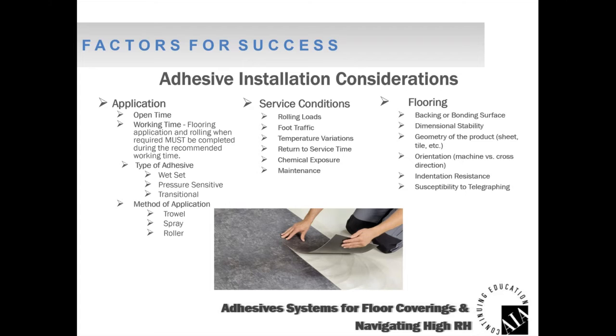Rolling loads, point loads, type of traffic, ambient conditions, return to service time. Can we return this to service immediately, or is there a 24 to 48 hour wait time for the adhesive to develop strength before you return it to service? Chemical exposure, maintenance issues. We've got to look at all those different service conditions when selecting an adhesive with a specific floor covering. And certainly the floor covering, you got to look at that as well.